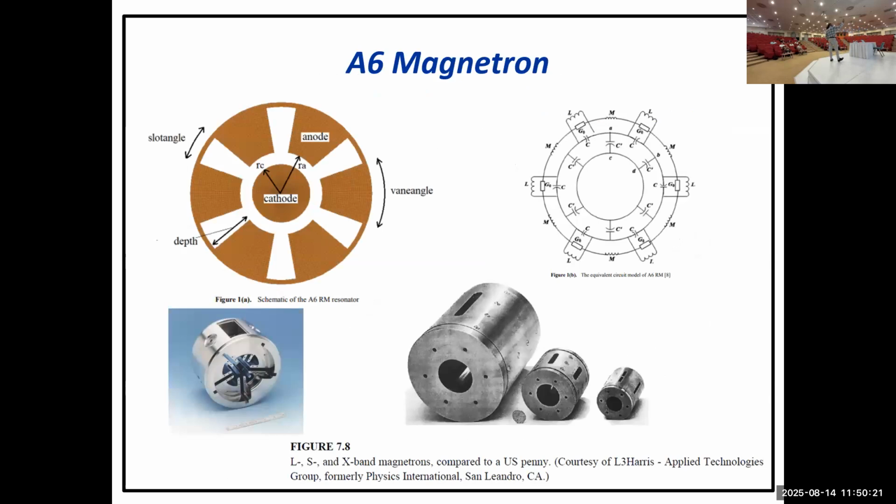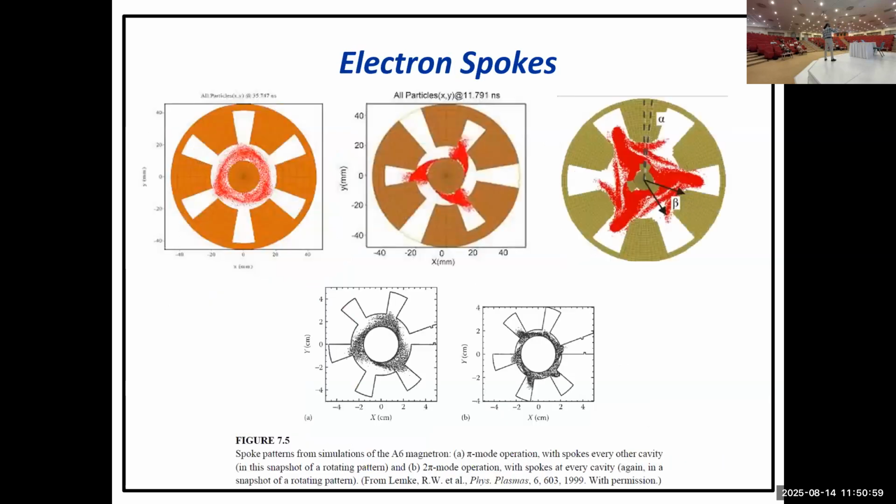You saw this, the equivalent of a resonant circuit. There is no actual lumped element, but we just approximate cavities as an RLC circuit, and this is just to understand, and you can calculate or approximate the operating frequency. But these are very rough approximations, not accurate. I think I showed this, but basically as you go up in frequency, your structure will be smaller and smaller. So the problem is you are limited with the power. Your breakdown is going to be limiting your operation.